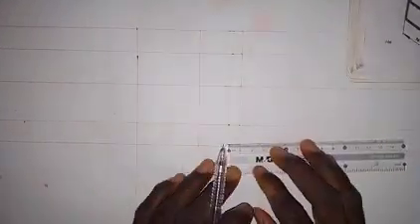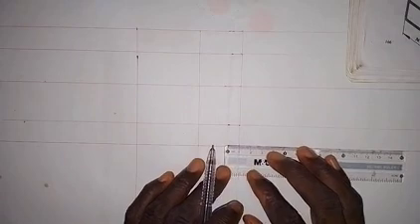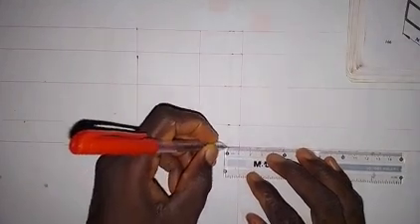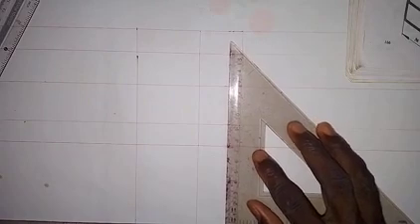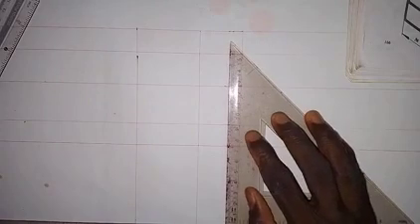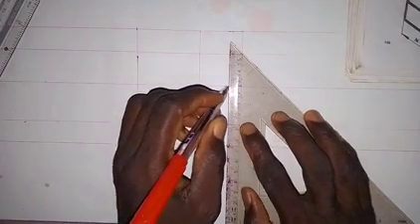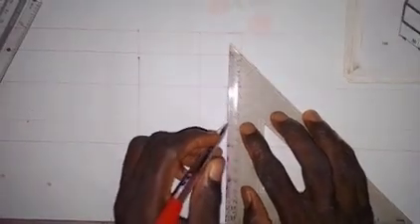So I need to take, sorry, the front elevation. So I need to take 10 millimeters from here. So this is 10 millimeters. That 10 millimeters, we need to make sure we show it. So I'm going to draw the vertical line. I only need it here for the front elevation. Then I will take it down for the plan.